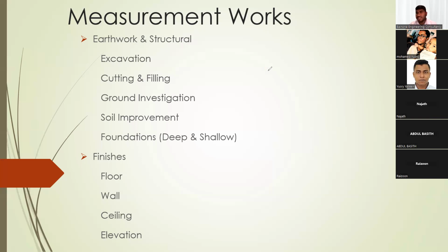Otherwise, as we mentioned simply, you know that the installation price stays the same, unless he changes the thickness or unless he changes the size of the tile. For example, he mentioned 60 by 60 in the tender. The same 60 by 60 is being installed, but the tile price is something different. So your installation cost still remains the same. So for example, here is 40, another X amount for installation, plus your overhead and profit.